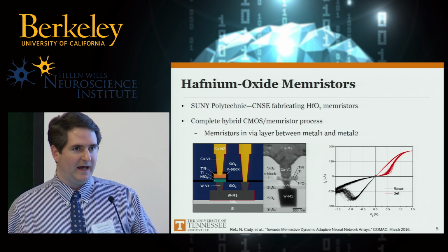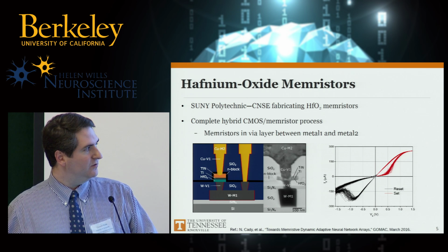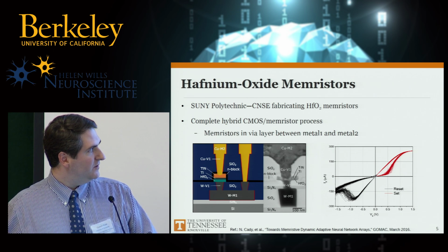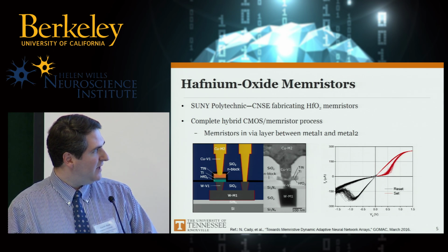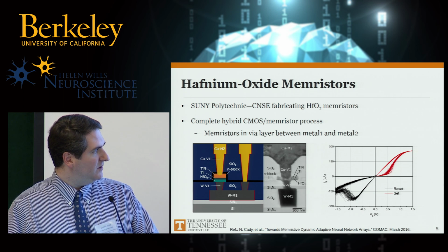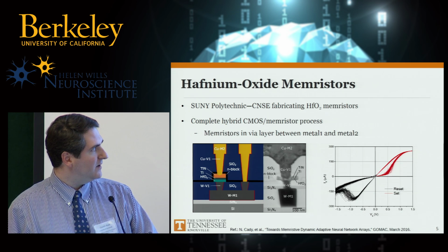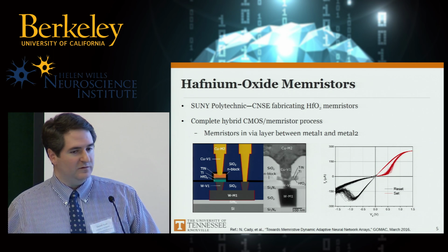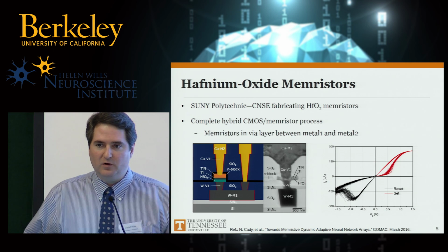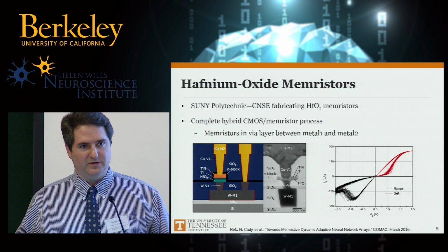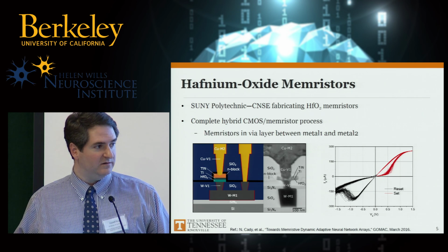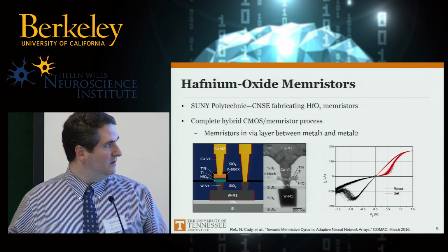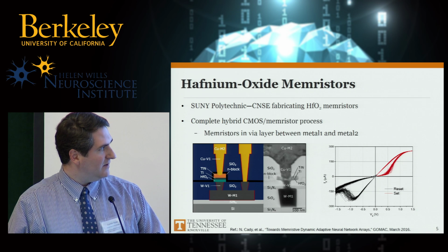So they kind of act as a fab underneath the umbrella of a university, in a sense. So they're able to integrate their memristors right on top of, you see metal 1 from the 10LPE process, and there's the memristor right on top of that, and right below the metal 2 stack. So it's all in line with the same process. So we're hoping that gives us some advantages in terms of how we integrate these circuits and some of these interesting systems. And you see the results for this hafnium oxide-based memristor.